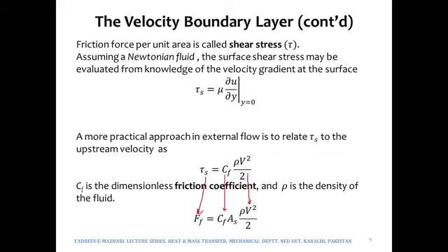So these are the expressions that we might be using while solving the problems. However, they are very simple equations. Tau s is half rho v square times the coefficient of friction, and tau can be written as force per unit area. Ff means frictional force, and tau s means shear stress over that surface, between the surface and the fluid.